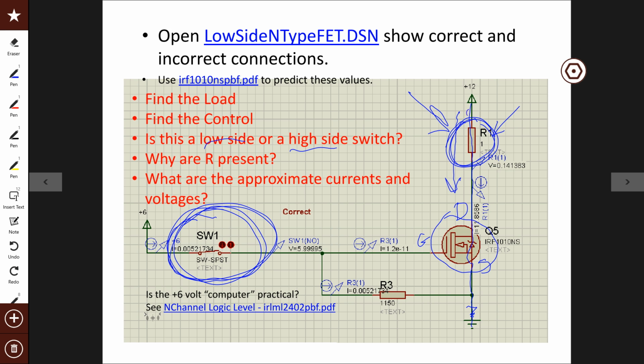One of the sides, either here or here, has the higher voltage when it's turned on. Well, the back side of a resistor right here, the tail side of the current, is always the higher side of the resistance. So this one right here is the higher voltage side than this one right here. Okay? So this is the big blue dot. That's the high side of the load. This, with the X, is the lower voltage side of the load when it's turned on, because the current is going from top to bottom, right? Because it's grounded here, it's high voltage here, so it's going to go from the top to the bottom.